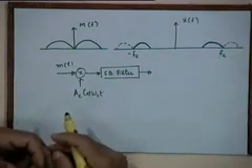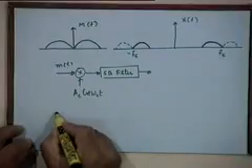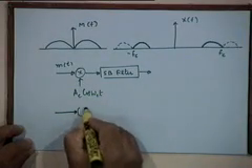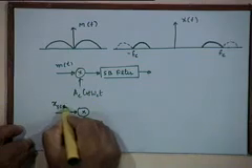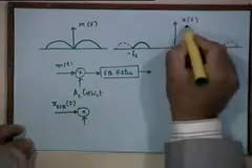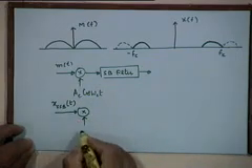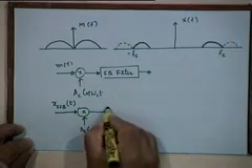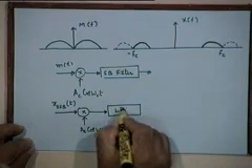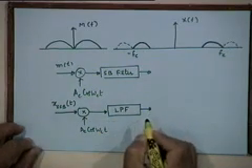If you want to transmit the upper sideband, you have to use a high pass filter or a band pass filter whose transfer function is non-zero between fc to fc plus B. So that's how you will choose a sideband filter. And like we discussed, the reconstruction is possible by the same process that we have for the DSB-SC signal. So here is your SSB signal coming in. This is your SSB spectrum, this is the SSB signal in time domain. You again multiply with the carrier and pass it through a low pass filter, just like what you were doing for the case of DSB-SC.